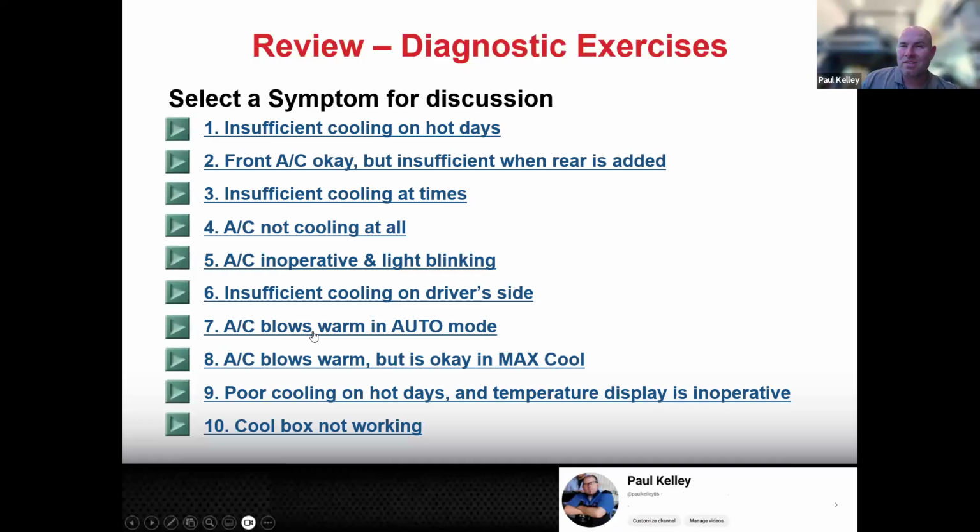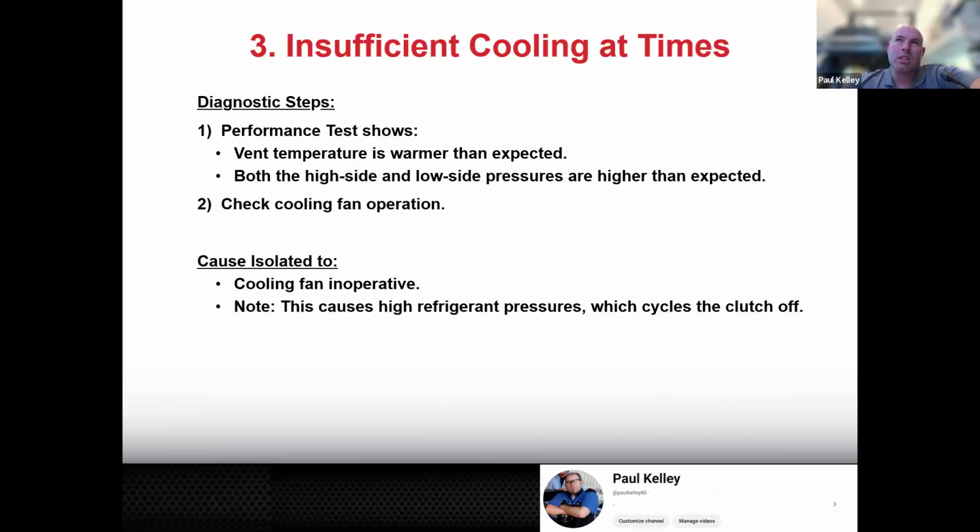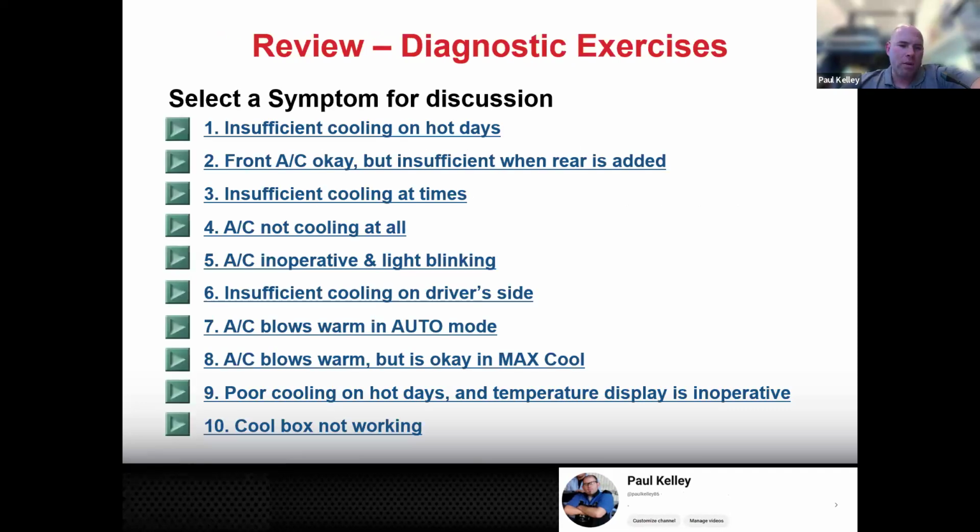However, this example was much more complex. There was actually a customizable mode in TechStream where you could change it from manual to auto. So somebody, this is totally unlikely, but in the customizable settings, somehow somebody put it in manual compressor operation rather than auto. I don't think you'll ever see that one. I like the temperature and solar sensor better. All right, how about